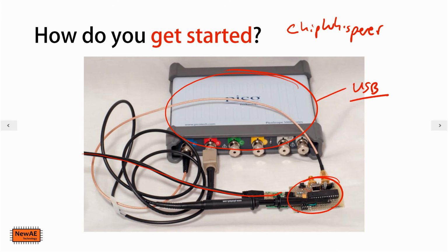Now, you need a scope with good USB support. So the PicoScopes are really good for this. They're probably the best USB scopes you can get. You can also use a regular scope that has fast data download, or Ethernet or something like that would work too. Some of the off-brand or lower cost scopes don't actually tend to work so well on the data download, so you should be really careful of that. We need a target, so this is an Atmel ATmega328P, so it's like an Arduino-ish device, and we're just loading encryption on it. And finally, we have a serial COM here.